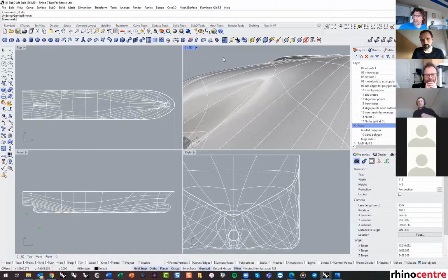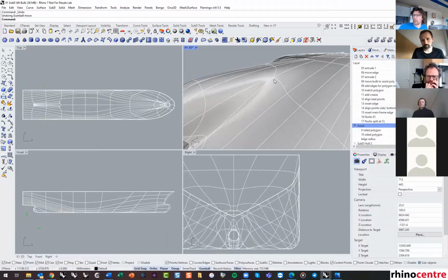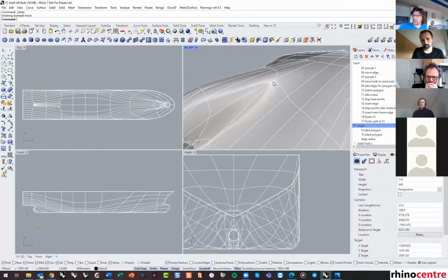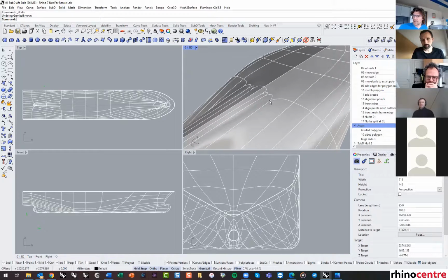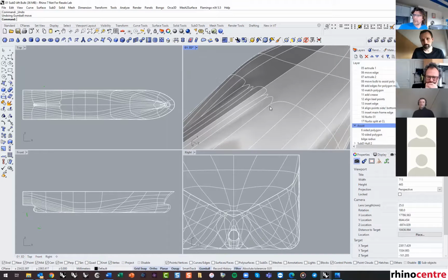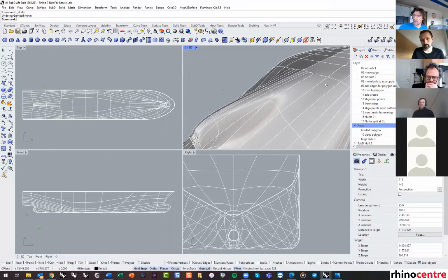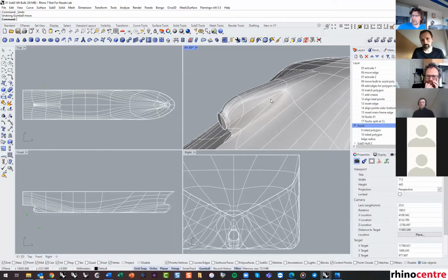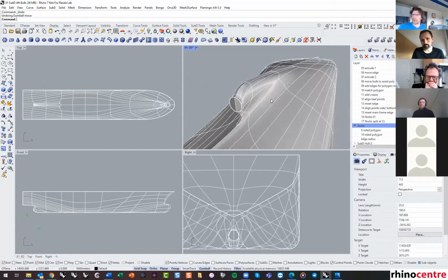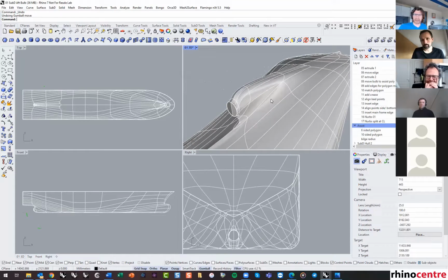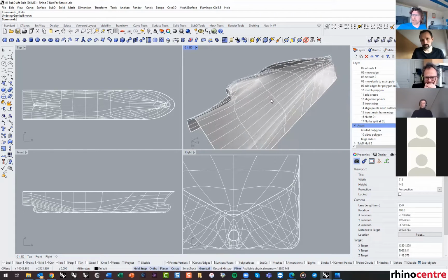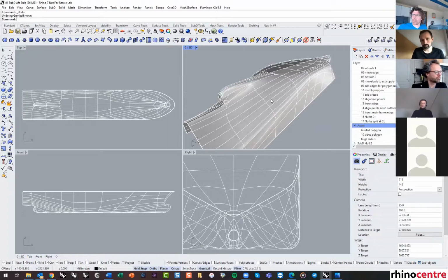As we learned earlier this afternoon, these points are still problematic in subdivision modeling. The same is, this is the 3 vertex point. So these are still challenging for Rhino SubD modeling, but for conceptual design, it's really fast. And again, in conceptual design, it's also useful that you can quickly analyze the hydrostatics, center of buoyancy, etc. So that's why I like this subdivision modeling already for the marine industry, but it's far from perfect for final fairing.